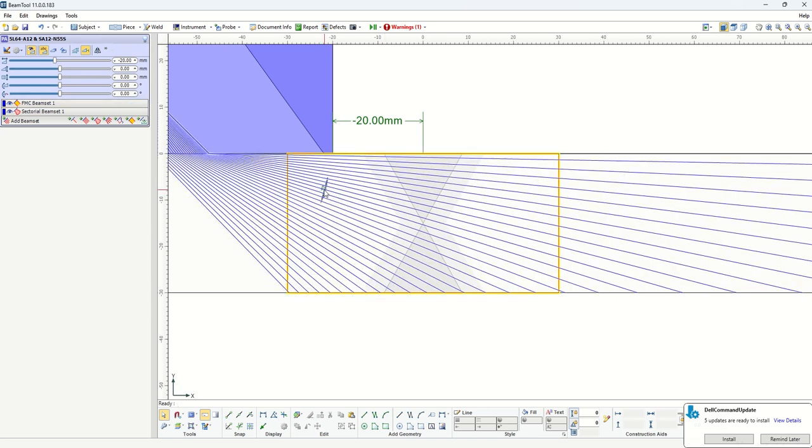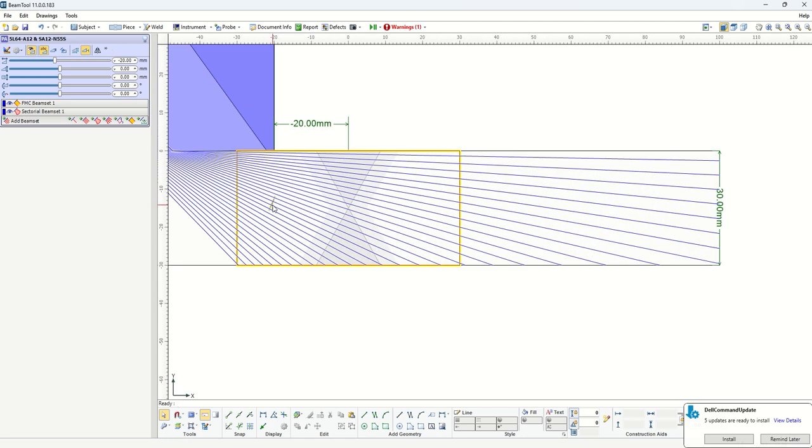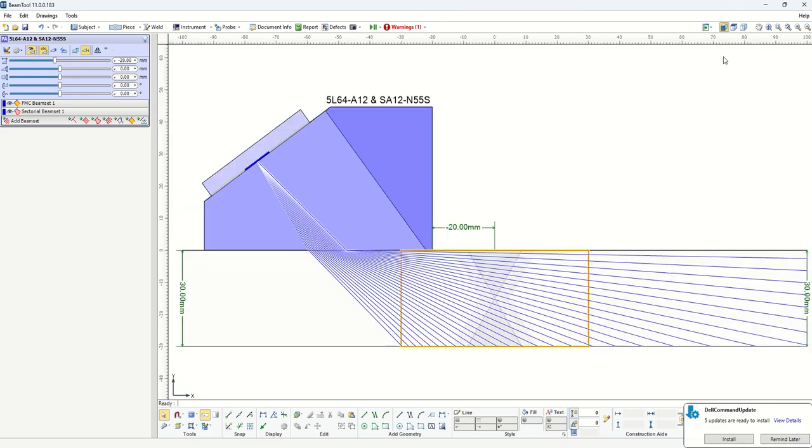And you can see that when I turn on the FMC beam set, at any spot when they are compared, the indication that we get, or the point spread function that we get, would be much smaller and focused for the TFM image from the FMC capture, but it's a very diverged, spread out indication for our phase array as compared to the TFM. So this example was chosen to just show you how we can also use point spread function for sectorial beam sets for phase array inspection techniques.